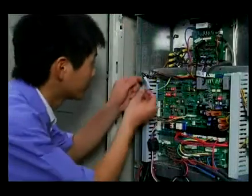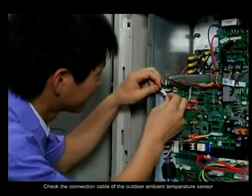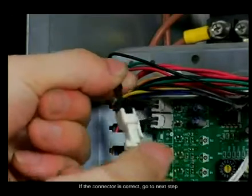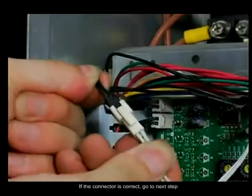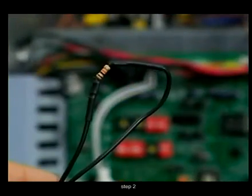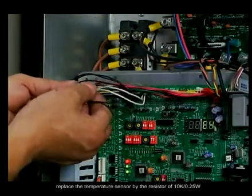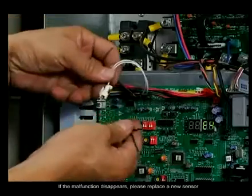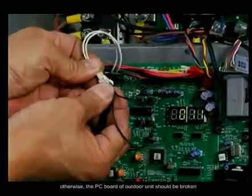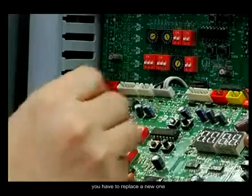Step 1. Check if the connection cable of the outdoor ambient temperature sensor and condenser outlet pipe sensor is reliable and correct. If the connector is correct, go to the next step. Step 2. Replace the temperature sensor with a resistor of 10K, 0.25 watts. If the malfunction disappears, please replace with a new sensor. Otherwise, the PC board of the outdoor unit should be broken. You have to replace a new one.